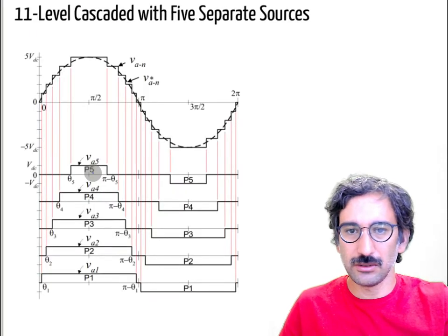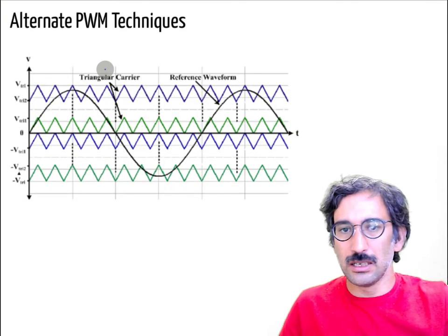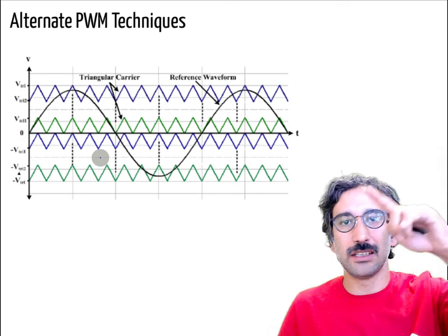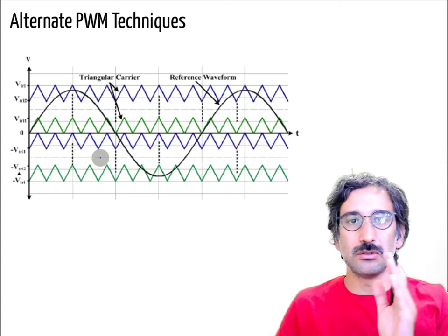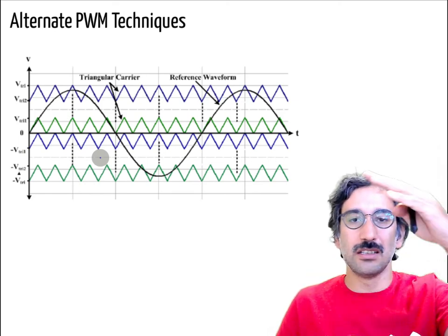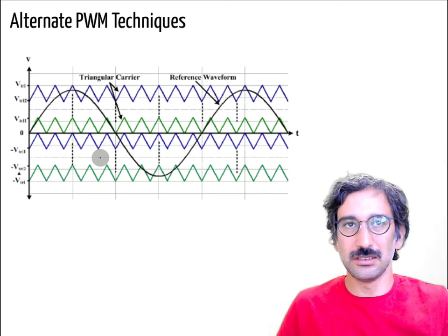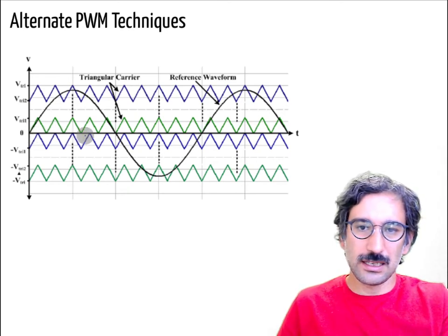But the simplest one that we can discuss now is, instead of using, remember, in a normal 3-level H-bridge controller, you will have a carrier signal and a reference signal, and you compare these two and just turn the switches on and off. And if your reference signal is larger than your triangular, you get into the overmodulation range, and the maximum overmodulation is just a square wave. So we are doing more or less the same thing.